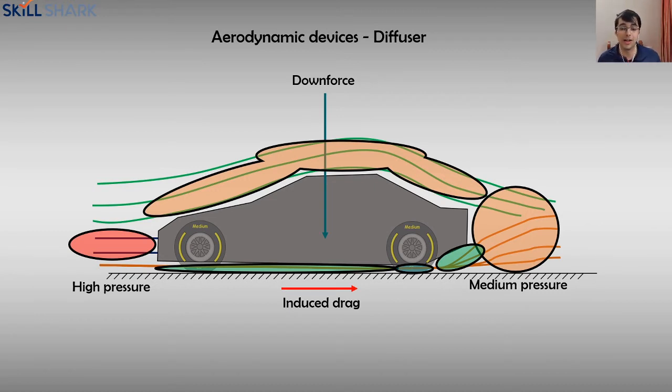So a diffuser reduces the induced drag and also adds downforce. So it's a very powerful device, overpowered to an extent. I believe almost 40% of downforce is generated from the diffuser in certain racing series. We won't get into the details of design. There are a lot of other parameters, maybe in a future episode, but it's a little beyond the scope of what we're trying to cover today.